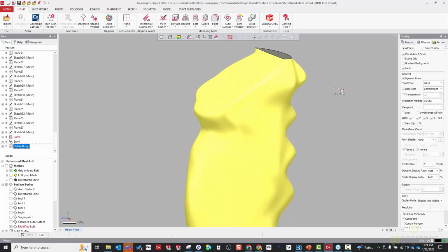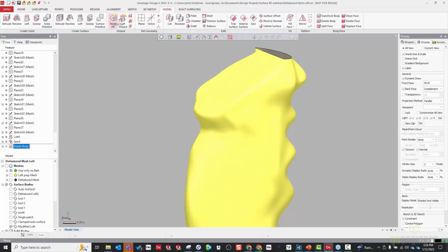You can absolutely do that. One reason that I chose to edit the mesh is I think it's a little faster to quickly close a hole in the mesh than to edit each individual cross section. Another reason is within DesignX, there's actually a loft wizard that will create those planes and sketches for me. So if I have a mesh that will generate a valid output at the beginning, that wizard will work better for me. But that's absolutely a valid way to approach that.